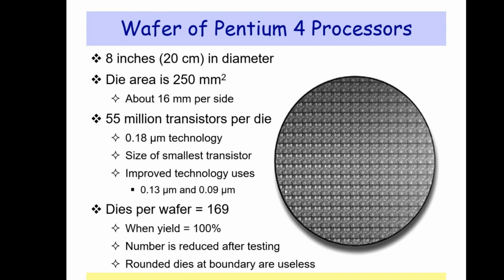Out of the number of ICs being manufactured by any manufacturer, if your probability of good ICs is less, that means your yield is less. Yield is the ratio of the number of good ICs detected to the total number of ICs manufactured. So your yield should be high, and for that, whatever you need to do, you need to do. DFT came into the picture in the first place because of yield.